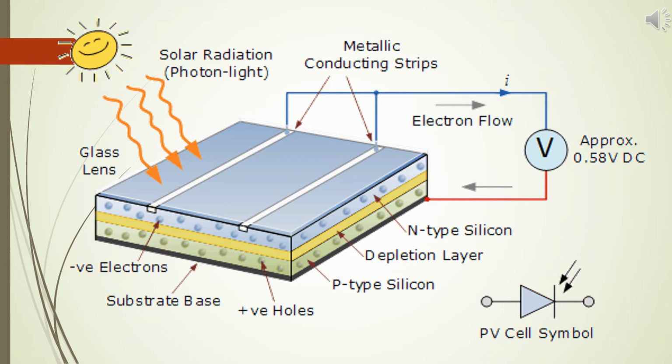A solar cell is made up of silicon, which is one of the most common elements used as a semiconductor along with germanium. A solar cell is one perfect example of a single p-n junction comparable to a photodiode. As shown in the figure, the n-type silicon side of the panel is what is exposed to the energy coming from the sun, causing an electron to flow going to the p-type side of the cell. On the contrary to what has been taught to us, that current flows from the positive side to the negative side, which is called the hole flow. The flow of charge in a solar cell is based on the electron flow, which is from the negative going to the positive. This flow of current is called the electron flow.